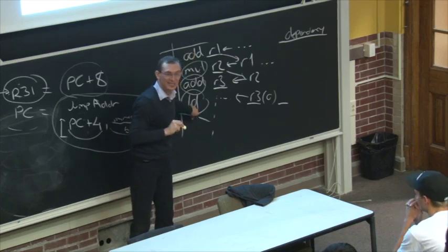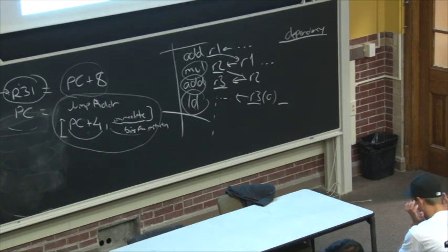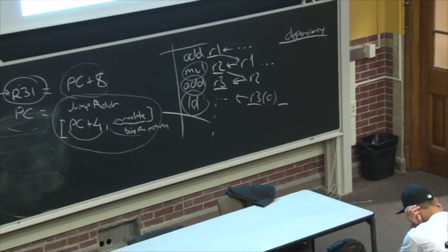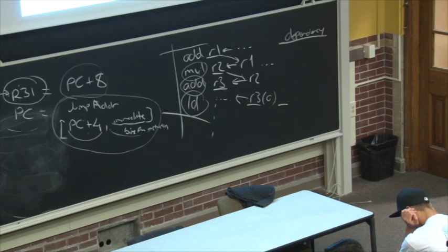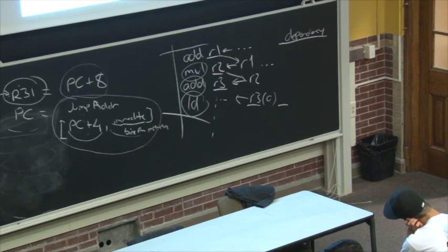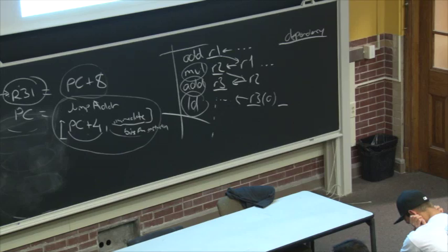But this is exactly the reason why, if you increase it, well, this is one example. If you reduce the cycles per instruction, you need that extra logic to figure out whether the instructions are dependent, which does affect your clock cycle time. Now you can say, I'm going to add another pipeline stage, not affecting my clock cycle time. If you add another pipeline stage, it turns out you're increasing the cycles per instruction again, right? Because it's taking longer to execute that cycles per instruction. So it's a trade-off. As an architect, you're trying to balance these different trade-offs.